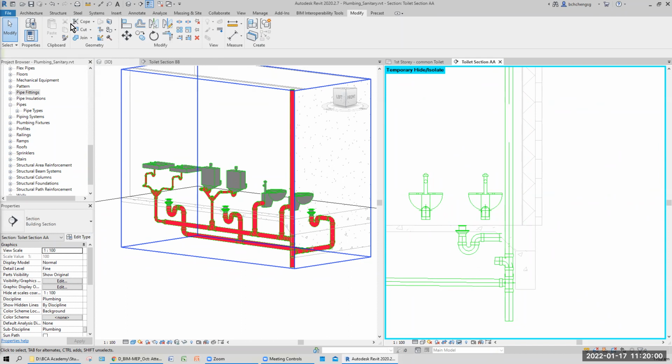In Singapore, actually, we don't have a separate component. They just add a fitting at the pipe itself. Because when the pipe has a bend, there's a fitting, there's an opening cap to open up. Every floor we have one. But here for this special case, we don't have that. So we have to add a fitting.